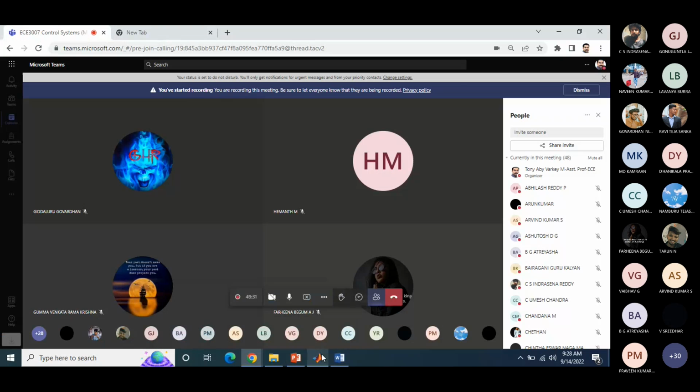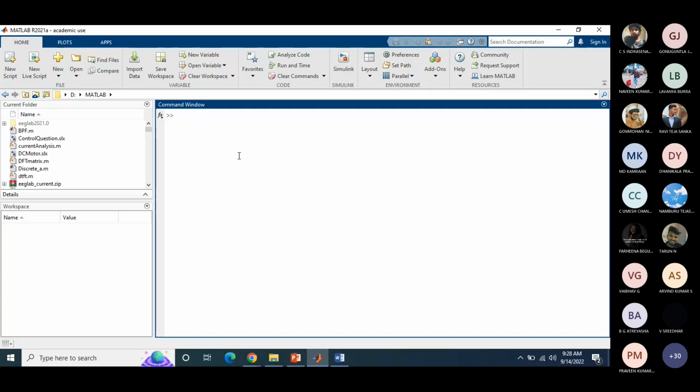Okay, I have opened MATLAB and it is very simple. What you have to do is first define t as a symbolic variable, like this: syms t, which means that t will be defined as a symbolic variable. Now I am going to give x equal to exponential of minus 3 into t. This is our symbolic signal. Now let us find the Laplace transform.